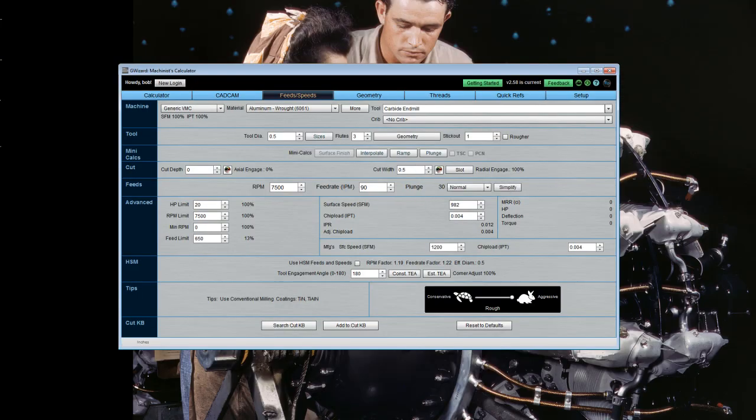Okay, that is stick out. There's also an option if you're using what a lot of people refer to as a corncob rougher. These are the end mills that have the serrated cutting edges, and they're capable of going a little faster and avoiding chatter because they break up the chips with those serrations into smaller chips. So they're really pretty neat, pretty useful. The mini calcs, again, we'll have other videos to talk about the mini calculators, their special purpose, and we just want to stick to the basics here.